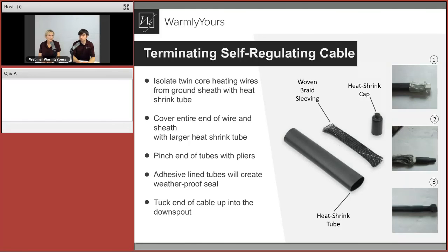I assume you're testing again after this. You still can test it. When we were talking about testing, we forgot to mention that you really want to test it at every major part of your installation. You definitely want to test it when you just receive it, just making sure it was not damaged in transit. Do some sort of dry layout, some section of the roof done. Test it again. You completed the layout, test it again. Maybe you worked with those aluminum 3-prong clips. Make sure you test it again, because you don't want to maybe cut it with some sharp edge. As soon as it's all secured and done, you can do your final test before and after your termination, and you're ready to go.